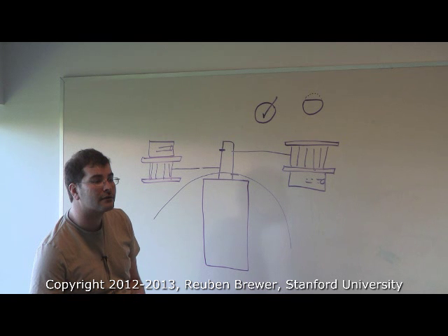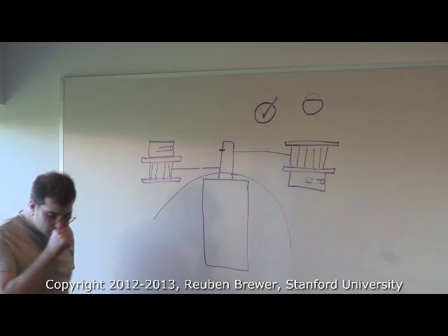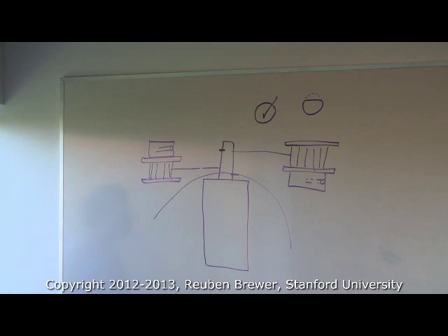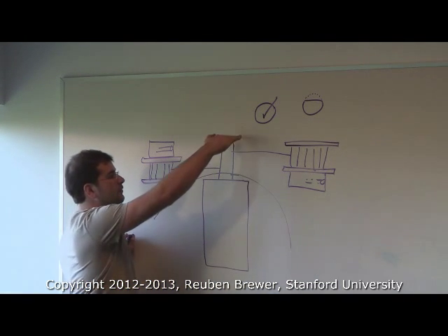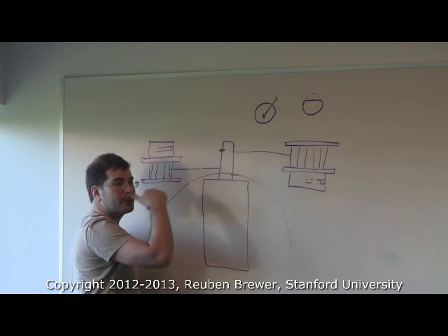But if you want to dremel a flat on your set screw, why would you dremel the whole shaft? Why won't you just dremel a little piece that will fit there, so you won't have that problem? You're right. Let me give you another thing. So you're saying don't dremel all the way down, just dremel this a little bit?